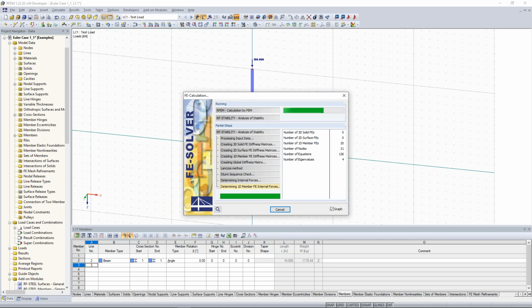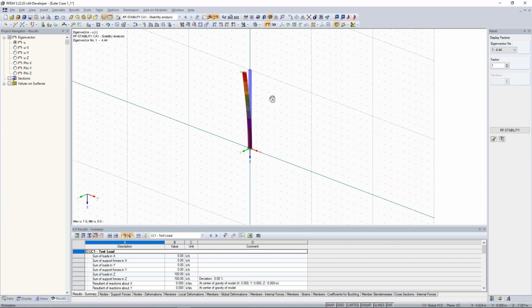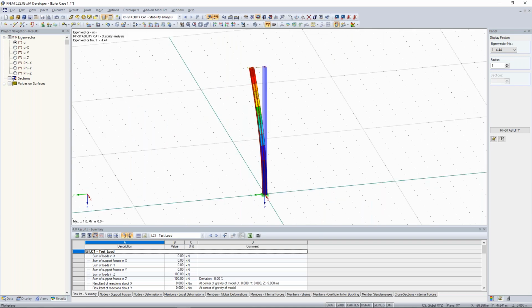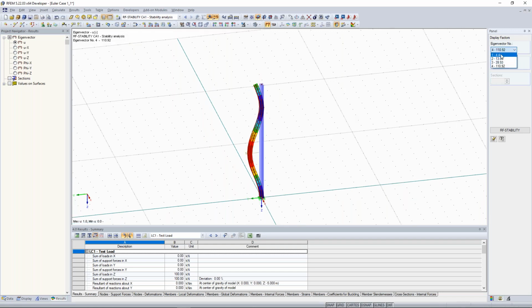a stability analysis, also referring to a design standard like the Eurocode 3, only the first cases are important for your design, because when you have here the area of stability, this would be the first fail if you would have too much nodal forces here. The second fail would be that. And the other fields, like 3 and 4, they wouldn't appear because this is too unrealistic. So this is also the reason why a structural engineer looks only at the first 2, 3, 4 eigenvectors.